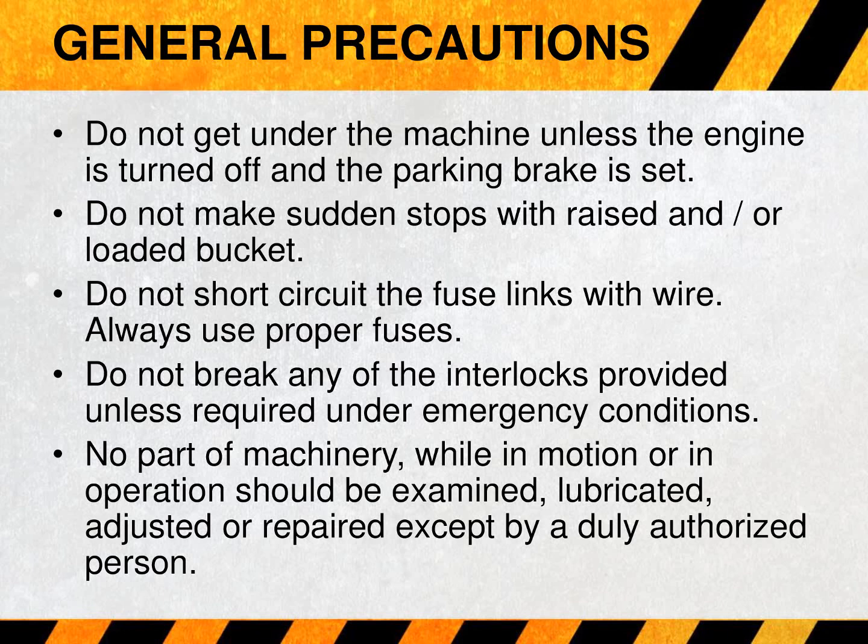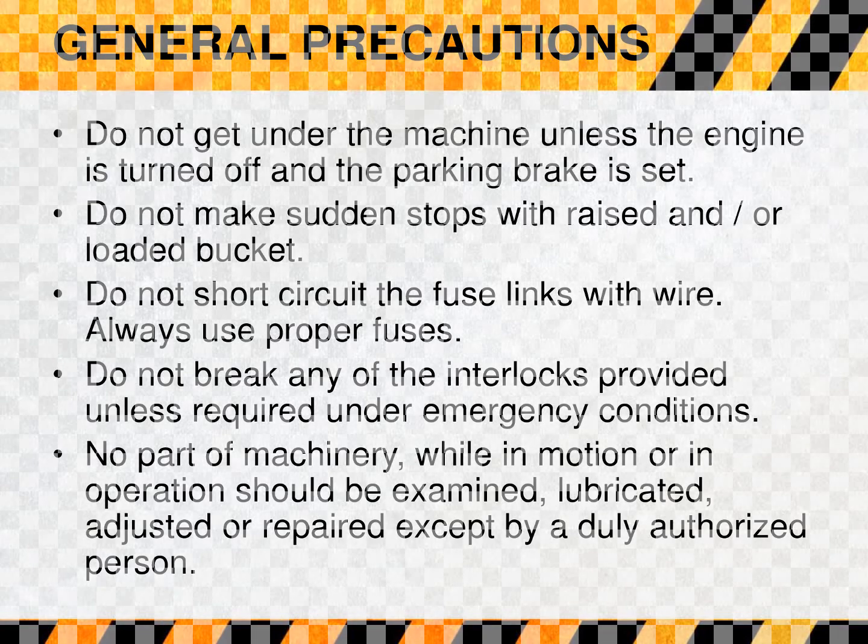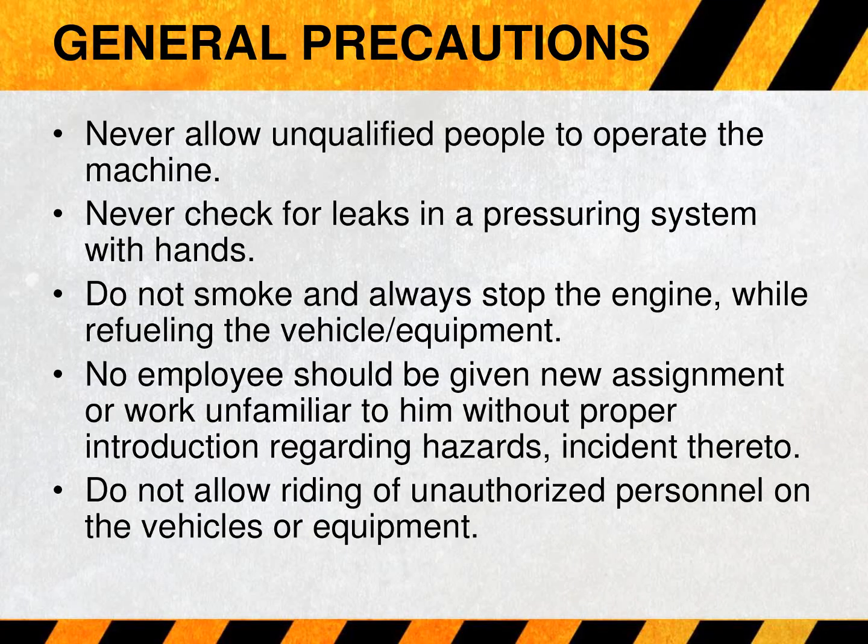No part of machinery, while in motion or in operation, should be examined, lubricated, adjusted, or repaired, except by a duly authorized person. Never allow unqualified people to operate the machine. Never check for leaks in a pressurized system with hands. Do not smoke and always stop the engine while refueling the vehicle or equipment.